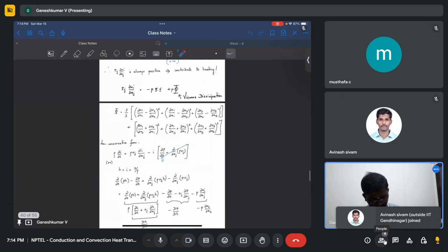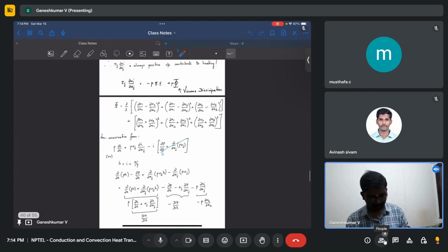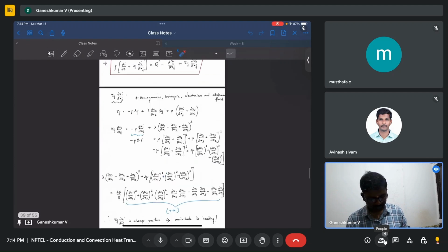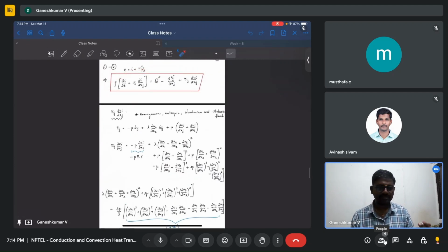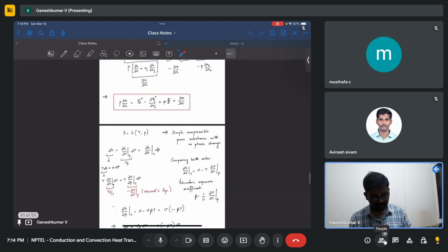Now, what we went forward with is from this internal energy term. Since internal energy is something we don't measure, we measure temperature, and temperature is what is important for us. So what we try to do is change this internal energy form into temperature form. For that, first we express the internal energy in terms of enthalpy, and then you simplify it. You can express this energy equation in terms of enthalpy. The only thing is, additionally you will have a dp by dt term.